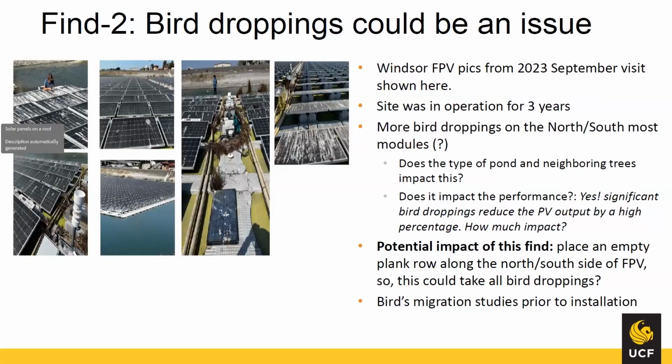If you cover one complete PV cell, you are making the power production in that subsection of the PV array less, or if the entire PV module is less, you're reducing the power in that PV module. If you see one entire string, suppose these PV modules are connected in different strings, yes, that could actually impact the string as well.